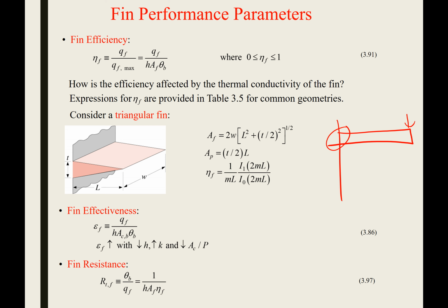At the right end it's going to be much less hot and closer to ambient temperature. As it gets closer to ambient temperature, the driving force for heat transfer at that end is a lot lower, so there won't be as much heat per unit length happening at the far right end. I'm saying this to make the point that these aren't perfectly efficient. Having the fin means you drop in temperature, which means your driving force goes down.